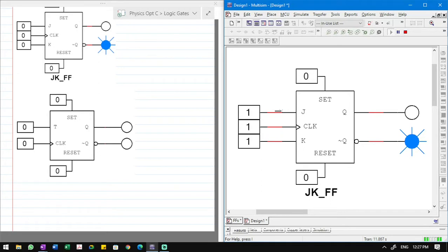Now, once you have either one of J and K off, nothing is going to happen, right? Typically, you would either have both of them off or both of them on. So in the operation we are focusing on, you want J and K to either both be on or both be off. So what you would normally do is tie those two inputs together, right?